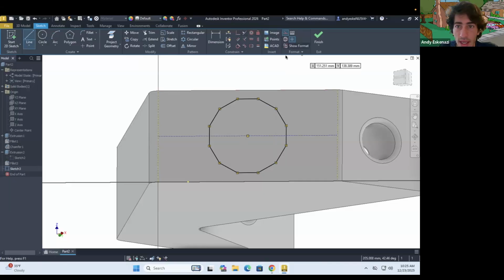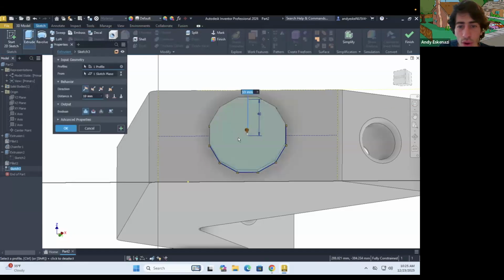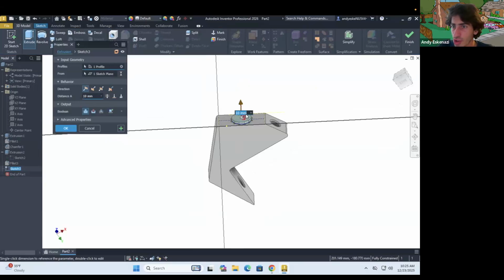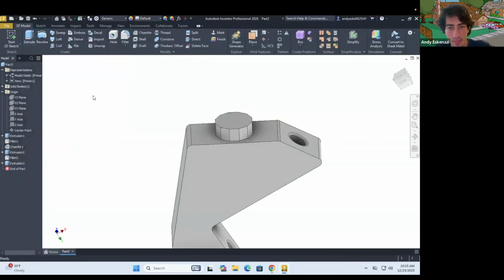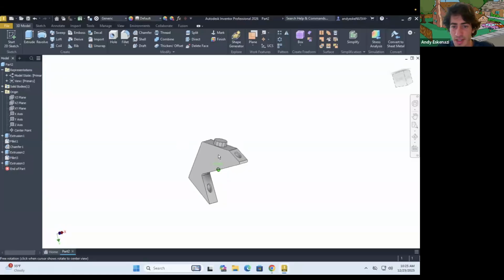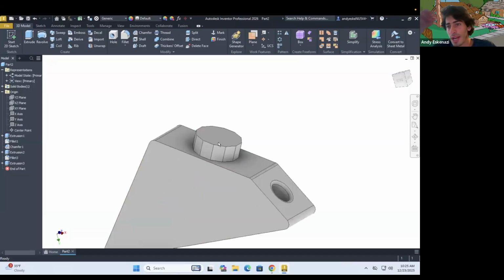And now I'm gonna make a construction polygon like that, another line, and I can say that I want that to be 40, and voila, that is parallel, and the inner diameter is 40, so now it's fully defined. So I can go here to 3D model, extrude, and I'm rotating using the ball of the mouse, and let's give that 30. Okay, it has some feature, right? Say if you want to place it in some other structure, that could be the slot, or that could be the pin that you would use to do that.